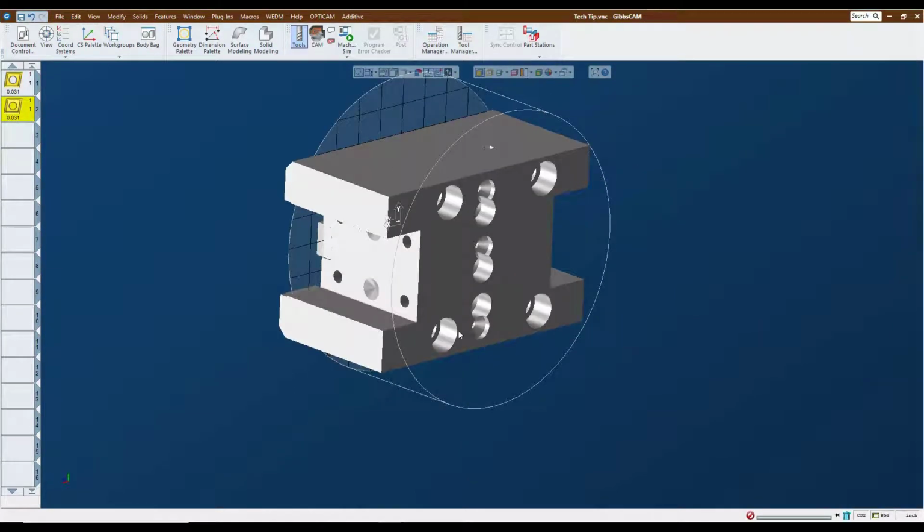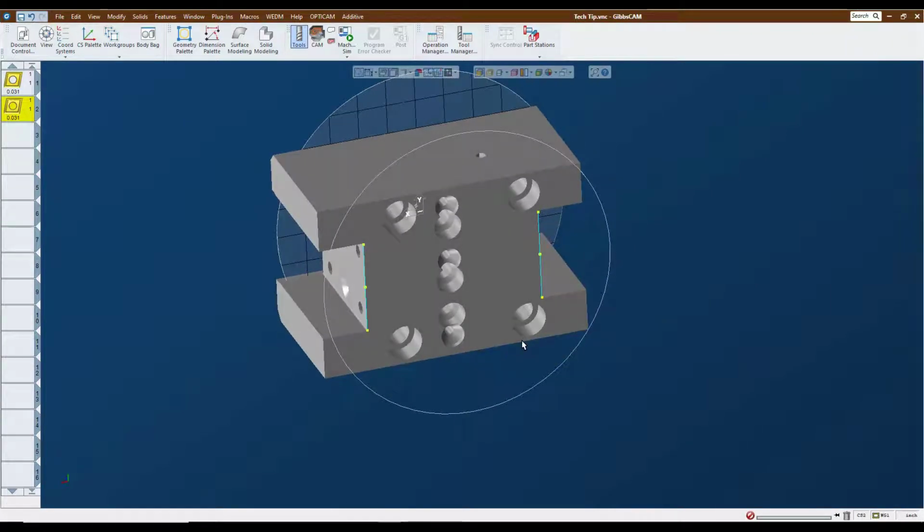Now on the other side here, we've got also some predetermined geometry. And in that, we're going to be utilizing the center line of these two lines here to position our attachment point coordinate systems. So I'm going to grab that line there, go to my geometry palette, and put a point in the center of that line. And then I'm going to do the same thing with this line over here. So those are going to be our coordinate systems for where our tools are going to be sitting for the left and the right hand side of this turret.